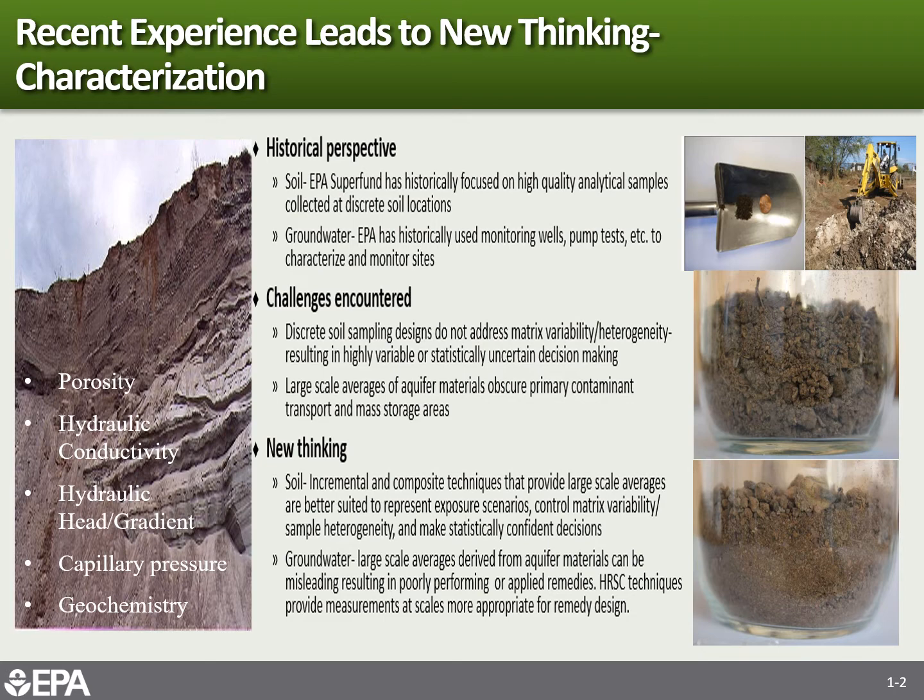In this case, our typical metals analysis in a laboratory is on the order of 1 or 2 grams. That's about the size of a US coin or a penny, yet we often make decisions that are on the order of acres or cubic yards or much, much larger volumes of soil. And the particle size effects can be quite dramatic.